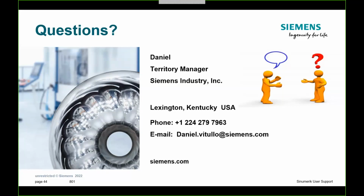Yeah, you're right. There is a lot of other commissioning, but the commissioning itself from the machine control side isn't really that bad. It's really a hardware limitation. So if for some reason your machine has a high-speed rotary, it could be something to consider. But more times than not, you would order the machine with it. I would agree with you there. It's not such a big deal if the rotary axis is designated with an S2 or S3 or S1, then it's seen as a spindle axis and probably has the capabilities to do it.